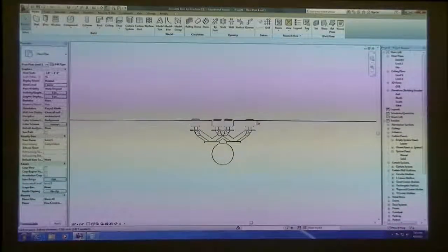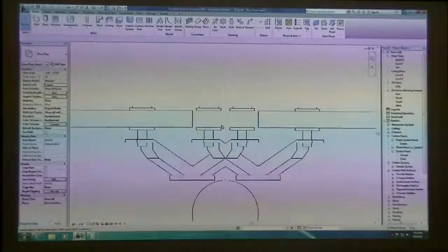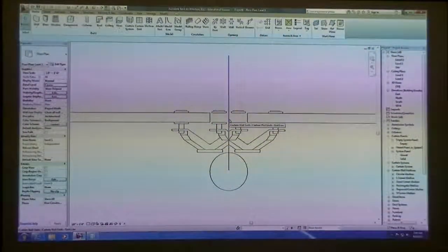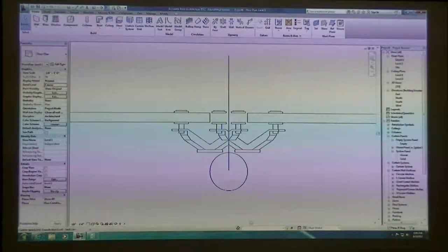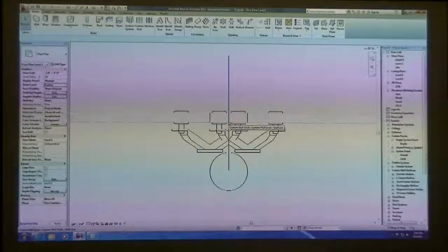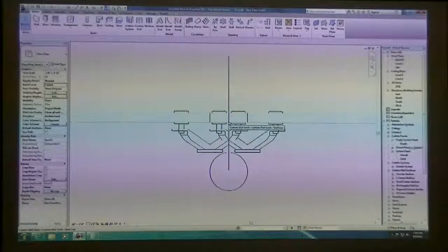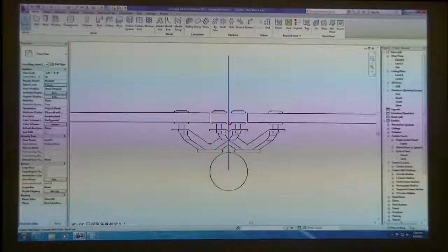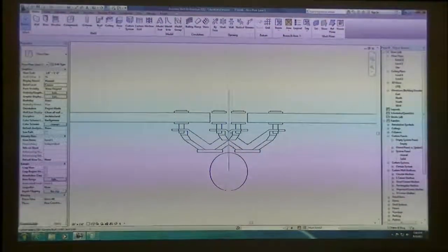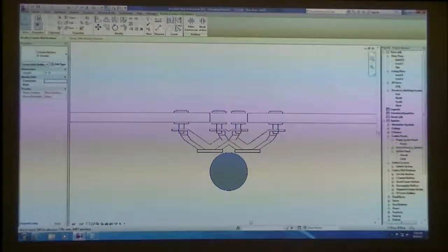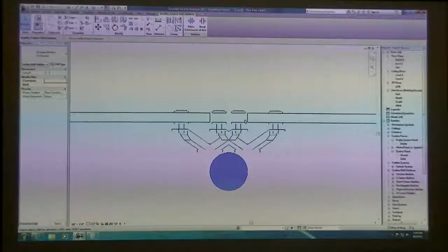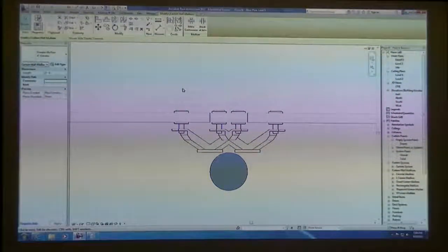So what we need to do now is fix this problem. Again, this is where we're recognizing what Revit does with the tool and then figuring out how we need to adjust it. We obviously need to come up with some sort of offset from those reference lines that were the boundary of the glass that we could manipulate and tell the glass to go back to its original location, which should be whatever the thickness of this circular, or this radius is. So we basically need this to offset 2 inches and get this glass to move back into place.